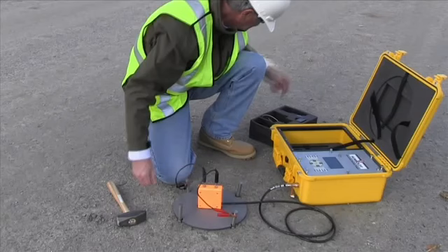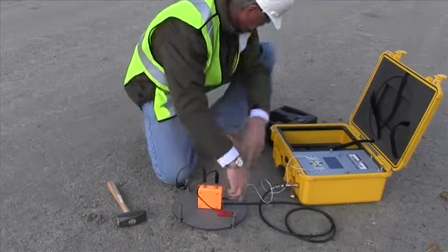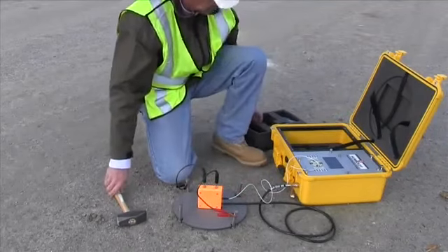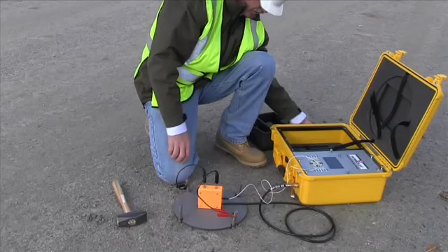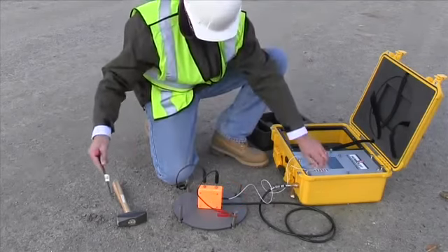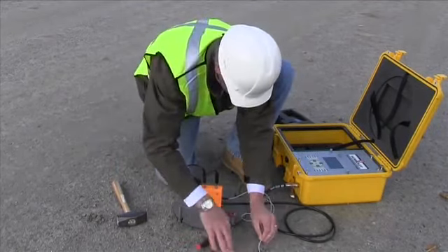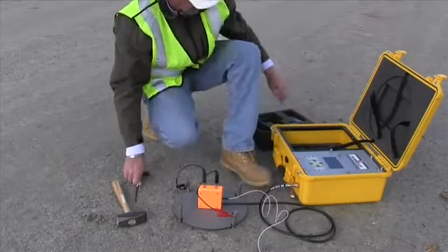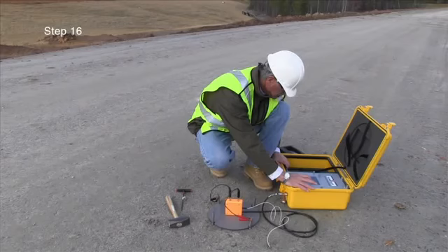Care should be taken not to cross the cables when switching them from the AA position to the BB position during the testing process. Remove the thermistor, or temperature sensor, located in its plastic case in the accessory caddy. Plug the thermistor into the mini phone plug port located on the side of the sensor unit directly above where the black cable enters. Remove the T-handle probe from the bottom tray of the EDG case and use it to create a hole away from the dart template into which you will place the thermistor. The placement of the thermistor is not critical and only needs to be placed beneath the surface of the material.